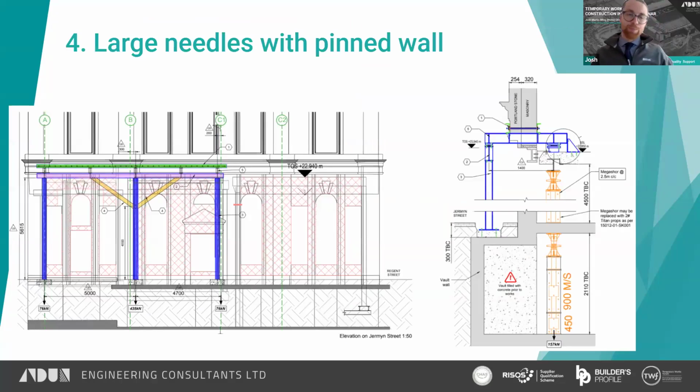Okay, so on to our next one. Let's look at needling with larger beams with a pinned wall. This was a scheme where the loads were really high because we were supporting a significant amount of the whole facade on this front elevation.